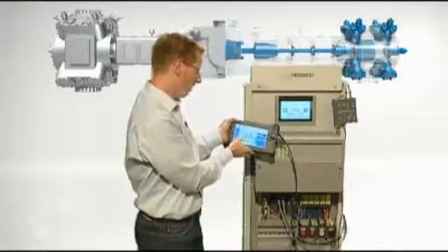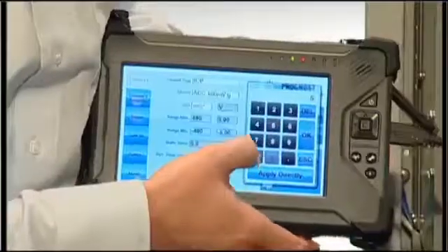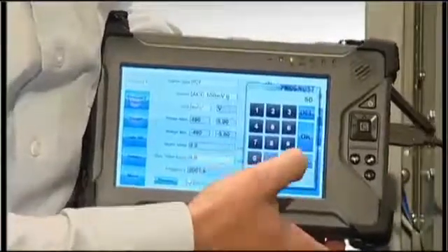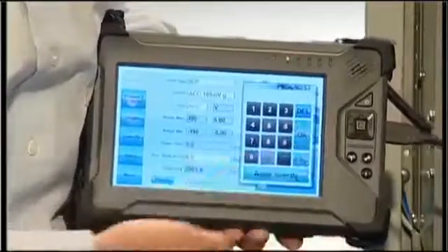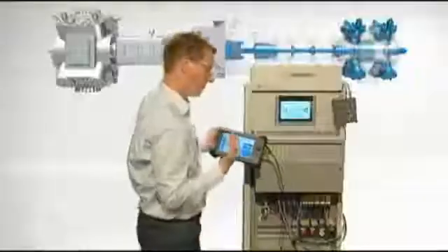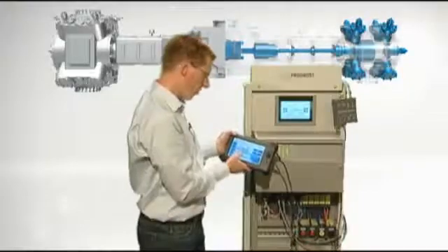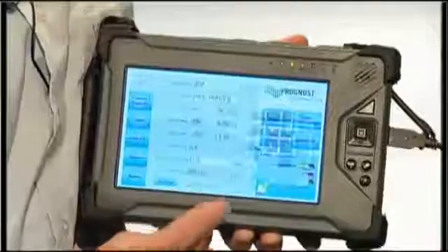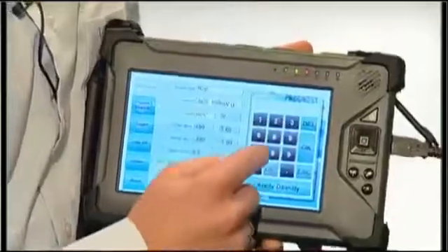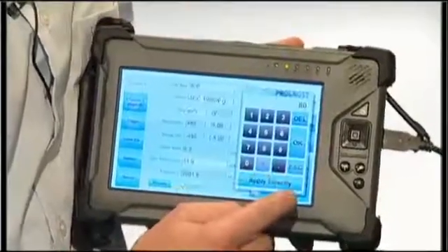We will now change the value from a dynamic RMS value from, say, 50 in a first go. We apply it directly, and we will see 50 meter per square second on screen. The sensor we now drive into the protection rack is simulating 50 meter per square second. Now let's go and violate the safety limit, slowly increasing to those values that are most applicable.